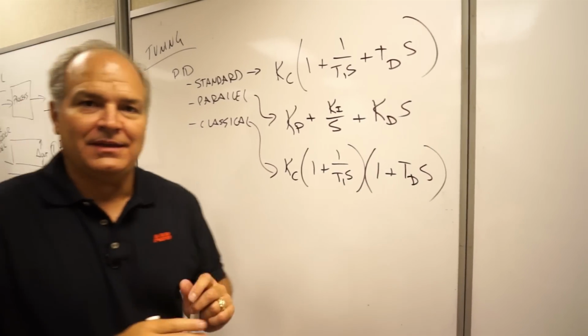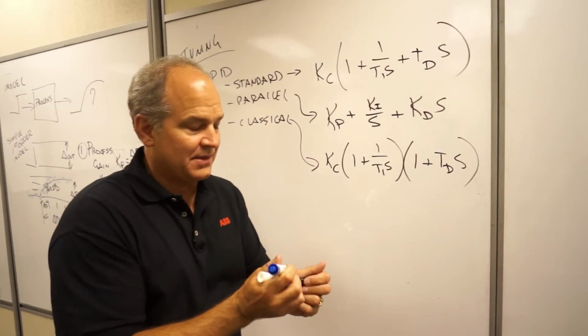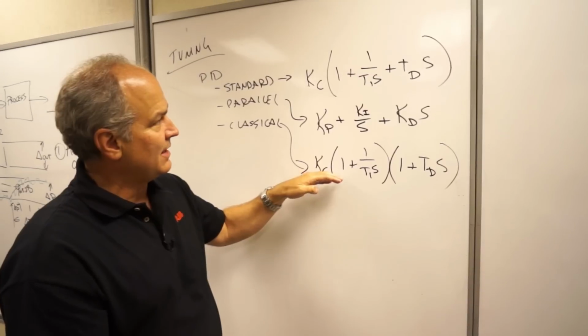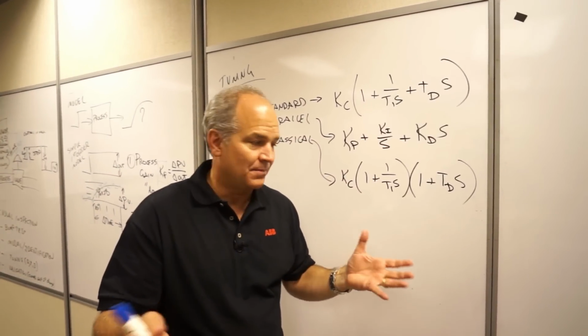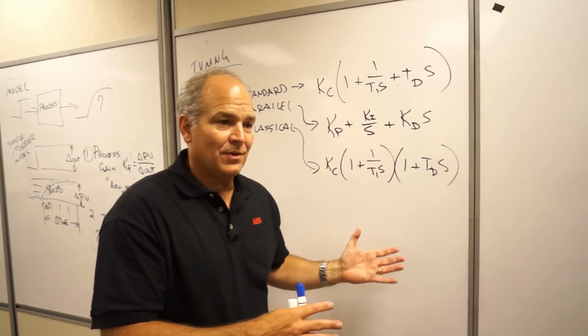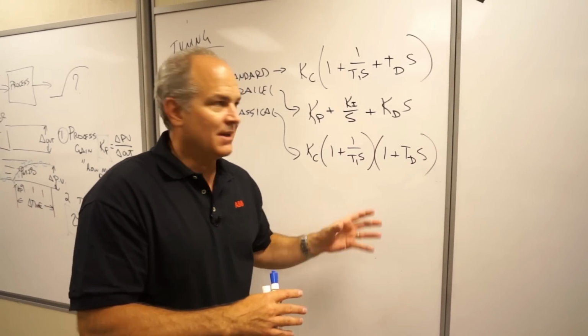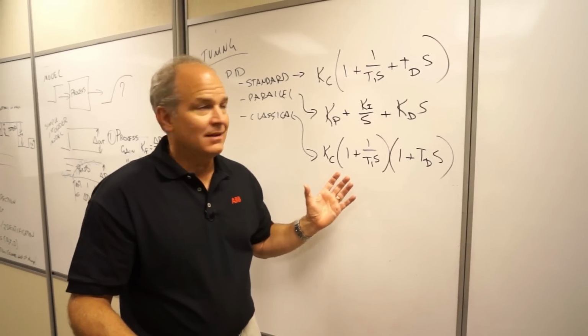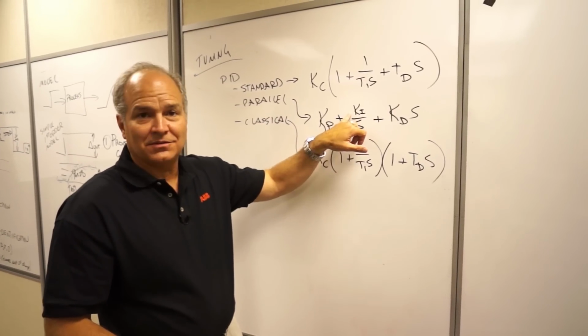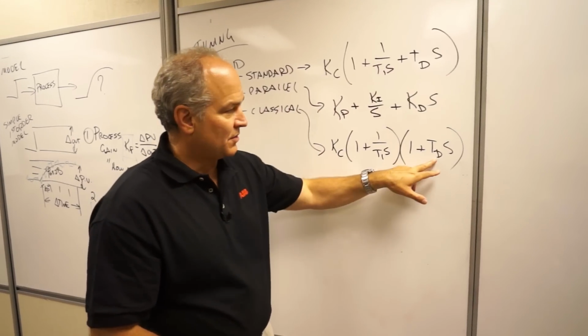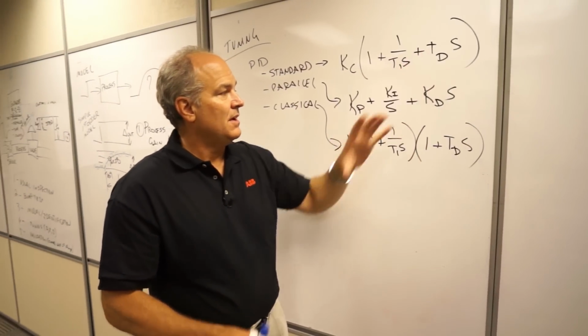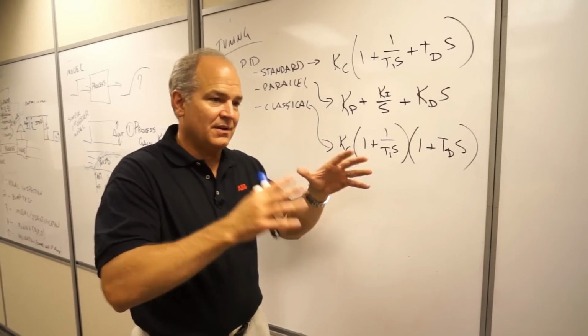I know this is a lot of math, but this is what the control modes look like, and I always have to go and look in the reference guides for our particular vendors. I won't name all the vendors, but not everybody calls everything the same thing. Some use an integral time, some an integral gain, some a proportional band, controller gain, derivative time, a derivative filter, all those different caveats.